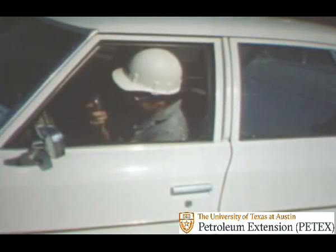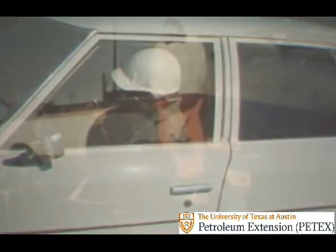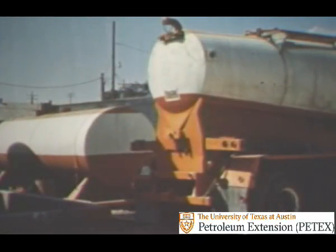The mud engineer at the rig calls the liquid mud plant and gives them the information needed to mix the mud for the job. Back at the mixing plant, the liquid oil mud will be prepared and transported to the rig by tank trucks. Any additional treatment will be done at the rig as required.